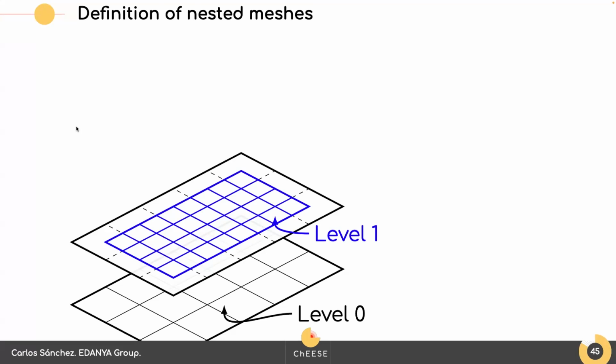And then after establishing the refinement ratio, we create a new subgrid. In these new points in blue, the points in the center of these cells in blue, we interpolate the finer data onto this grid. So to pass from level 0 to 1, we select a reduced area or reduced extension of our domain.